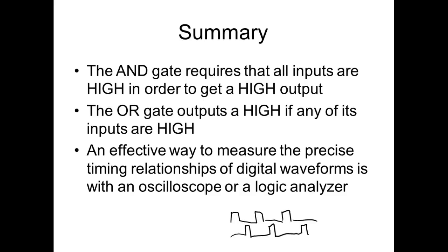This is just in our bones, you know, it's hard to see that. If we had a scope, we could put this on there, but if we add another signal in here, and we come over here and do this, then the output would still be low, right? You understand? So if you just see pulsing, which is what a logic probe is going to show you, they work real good for static, but they work very poor for pulsing signals. An oscilloscope works okay on 2, but if you've got 3, you're messed up, right?